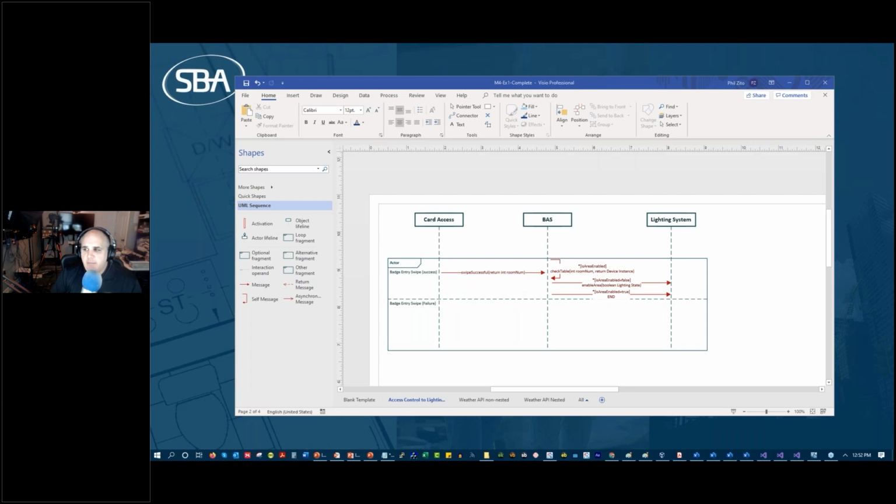What I really recommend for developers is understanding the ASHRAE 135 standard, and understanding the data types required for the functions as well as the returns. Especially when you're dealing with MSTP and somewhat BACnet IP, understand the data formatting, APDUs and NPDUs, and the BACnet virtual link layer, the BVLL. We cover those at a high level in that course, and definitely at a deeper level in our BACnet protocols course.